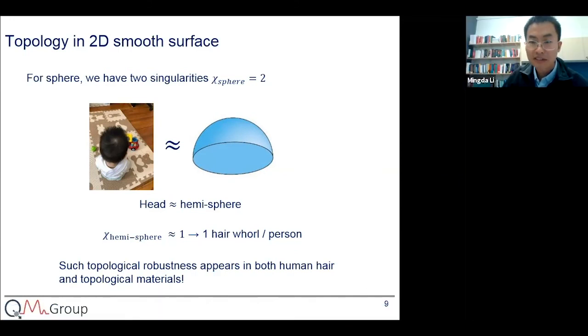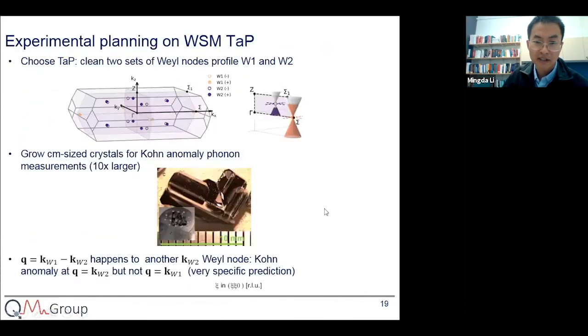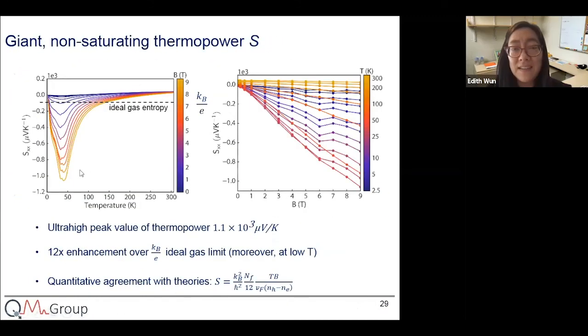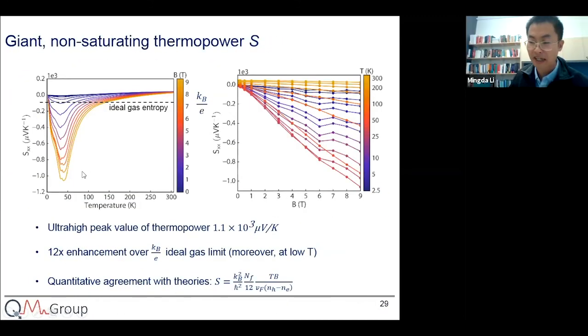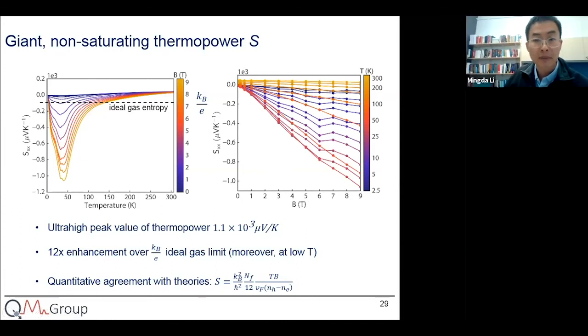Yes, that's a great question. For these particular materials, it's below liquid nitrogen temperature. If we want to do something at a cryogenic temperature, we use liquid helium at 4 Kelvin, liquid nitrogen at 77 Kelvin. But with thermoelectrics, if we run it backward, which means we inject current and make it cool, as in the Peltier effect, we can do cryogenics without using nitrogen or helium.